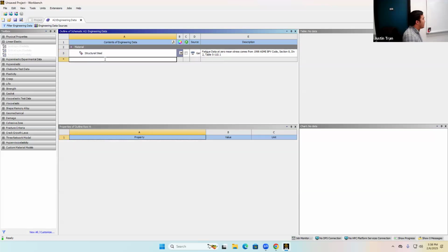So for today, I'm going to show you how to add a material from scratch. And so, just to show you how to manually add the materials yourself, there is a material library within ANSYS. We will make use of that in future activities. But for today, since we're going through the trouble to add a material, I'm just going to show you how to make one from scratch.